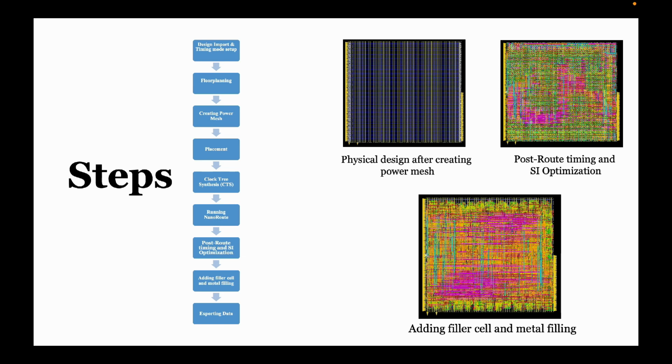Next comes clock tree synthesis. Now we need to synthesize the clock tree for this design. To do so, first we have to set clock route and clock tree settings. Running NanoRoute. Though timing is already closed in this design, we need to know the NanoRoute approach. In general, timing is not closed on a design unless crosstalk is prevented, analyzed, and then fixed. To achieve the above, the design is run with global and detailed routing using NanoRoute.